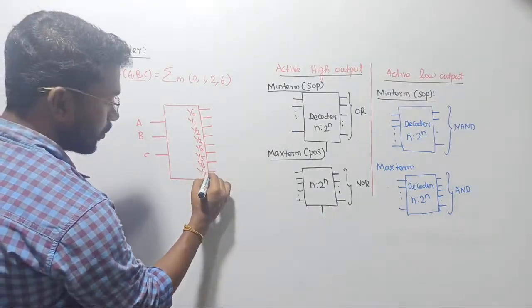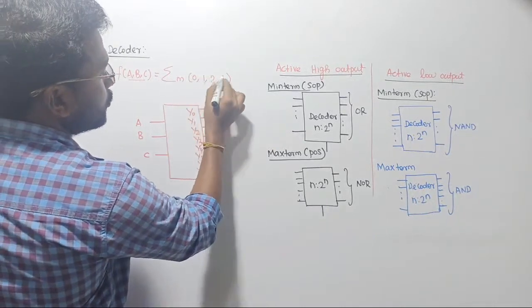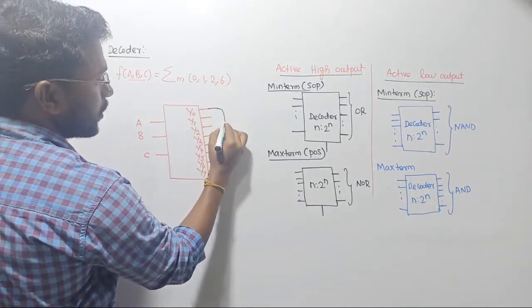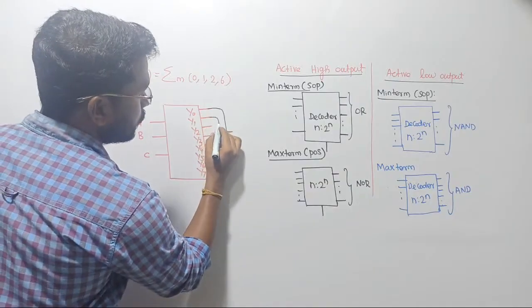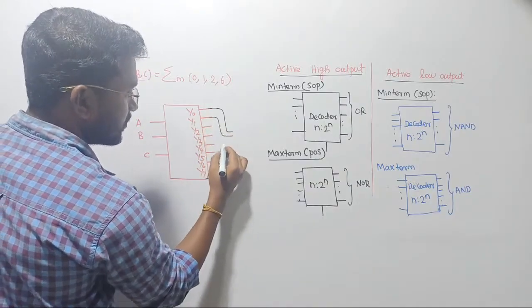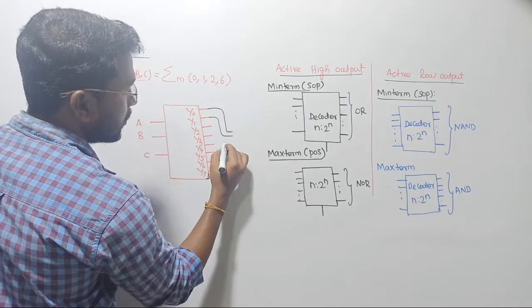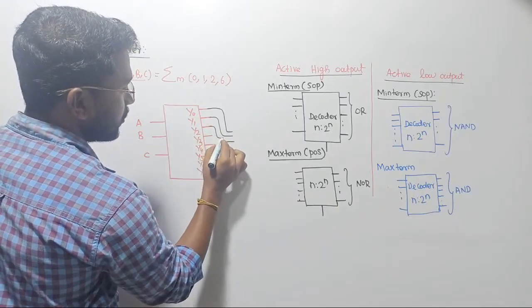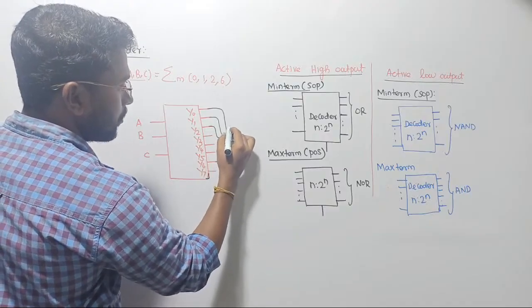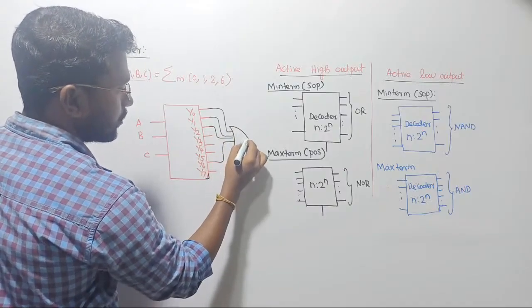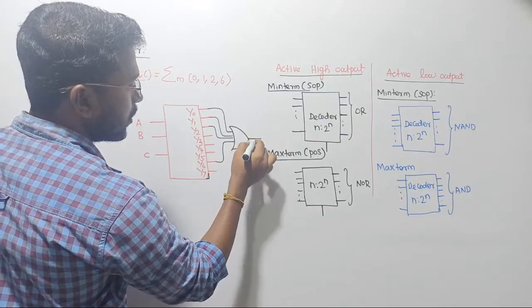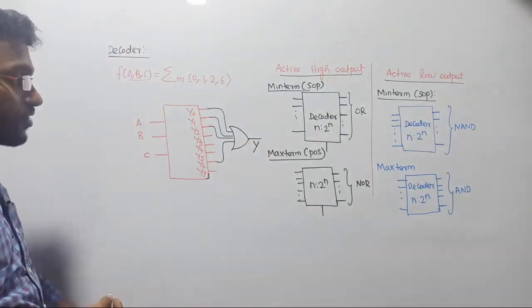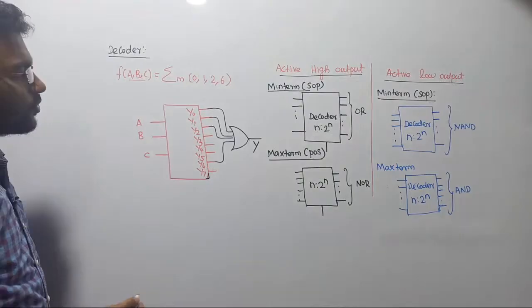That is a very simple circuit, right? How will you do that? 0, 1, 2, 6. Which is 0? This is 0. Where is 1? This is 1. Where is 6? And this is 6, right? So this is going to be our 6, and 0, 1, 2 also we are going to consider. Simply merge them with what? OR gate. That's all, it's over. That is going to be our net output. Any doubts now? There is nothing more to write.